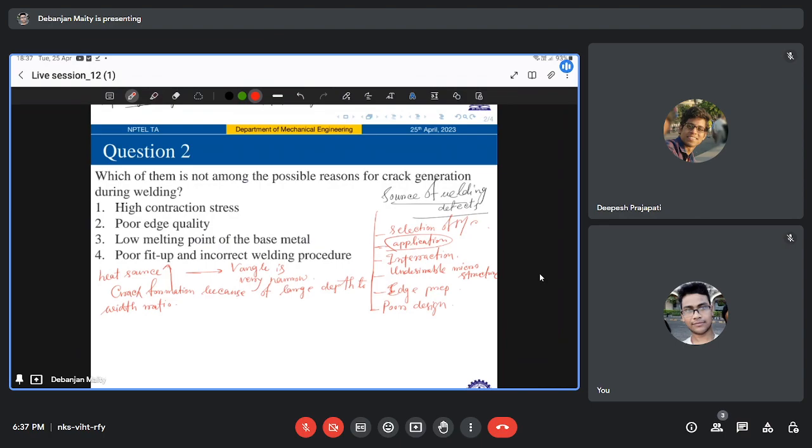And then in terms of interaction of weld metal with prior defects, what I mean is that many times it happens that the weld metal will be interacting with the defects which are already there in your sheet metal or the base metal. So basically you will have this lamination, and impurities like phosphorus or sulfur. Those things are there, right?